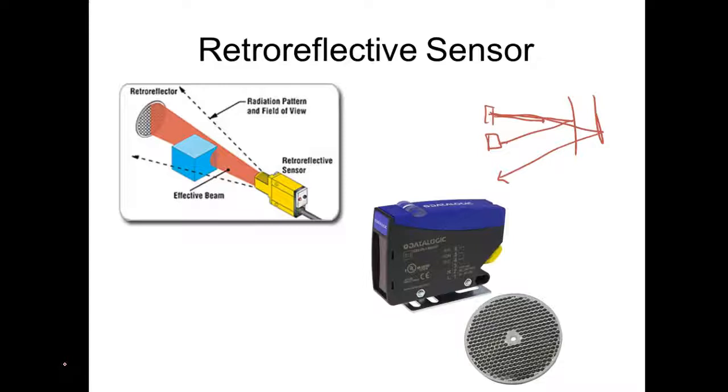Solid state sensors, by the way, DC sensors usually use a transistor as their output. But you can buy the sensors that use a relay, use a little reed relay in there. A reed relay is pretty neat. They'll put a reed switch in there, and then they'll wrap a magnetic coil around it. And then now you got what we call a reed relay. So if you put this in here, it generates a magnetic field, what would it do? It causes a little reed switch to close. What's nice about the sensors that have these outputs is that these things will switch DC or AC.